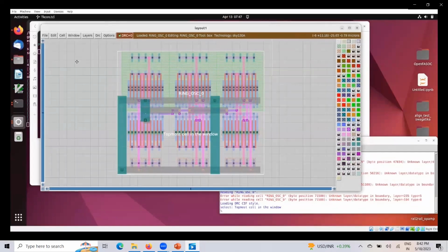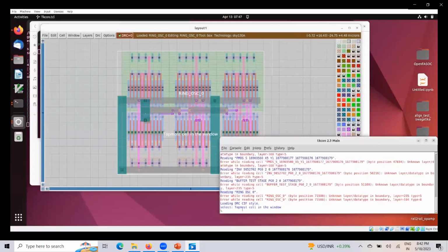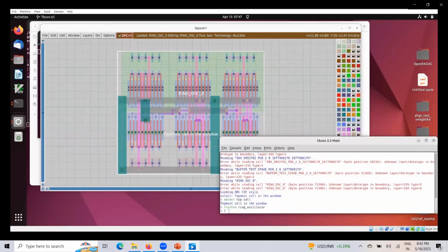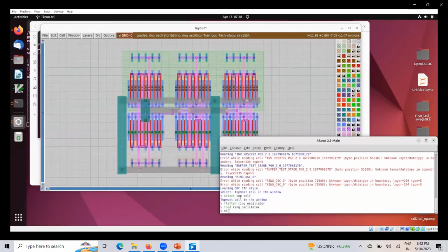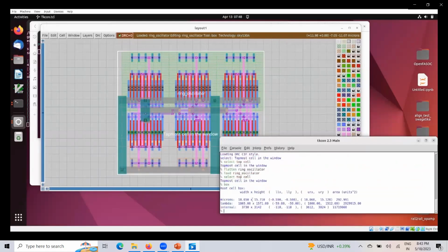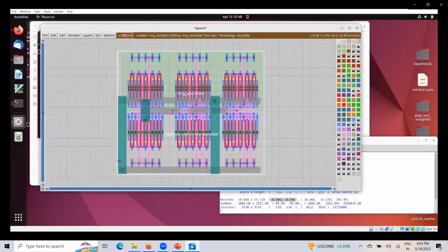Another thing that I just missed is here we can see where the box is present, where the whole GDS layout starts from. We need to ensure that it starts from the origin itself, because after the OpenFASoC flow I saw that if we skip this step, then some of the GDS macros were not in the desired position, so they were off by some pixels. Yeah, this is where you see that it's off by minus 0.59 microns.